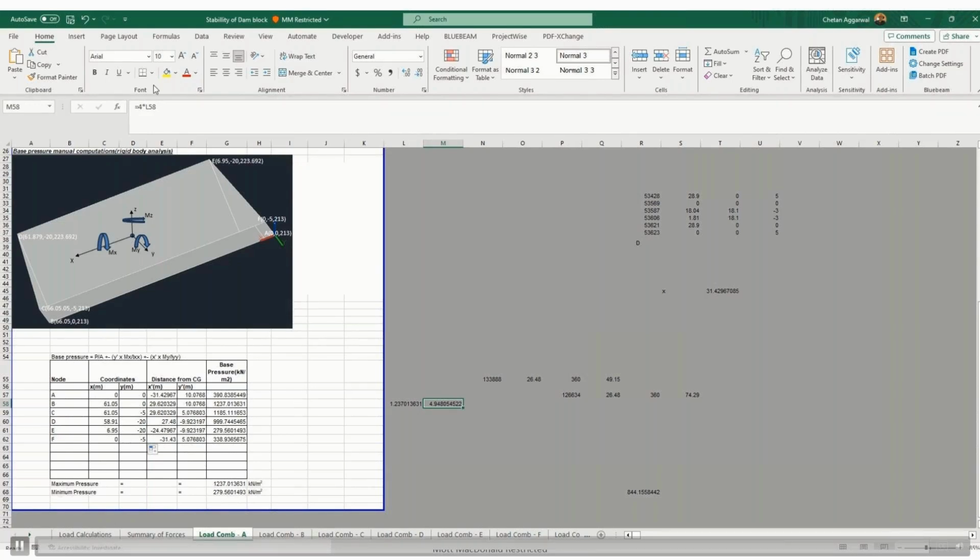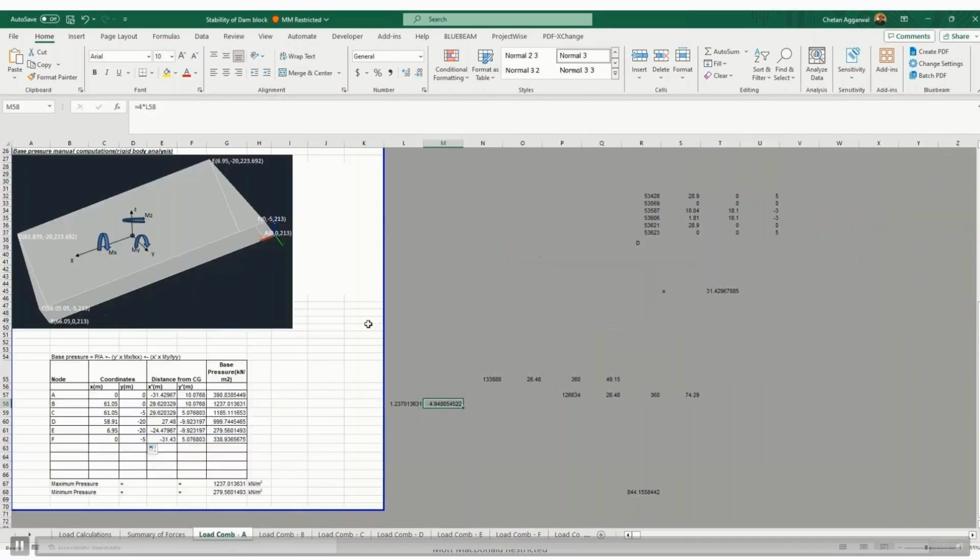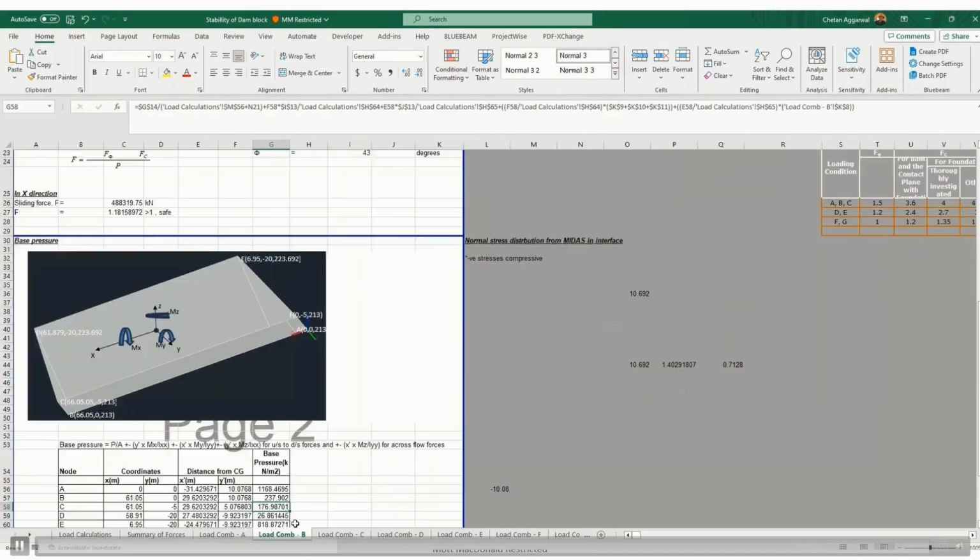This factor of safety and unconfined compressive strength you should get from site results, and your geotechnical engineer will suggest what is the safe bearing capacity of that rock. It's a high dam. A high dam should be founded on sound rock, so it should be provided. This is just a check from my side. I was talking about the torsional effect, so I'll discuss it here.